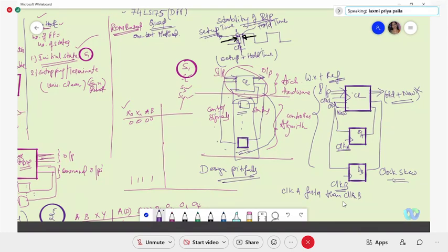That's equivalent to the D flip-flop. Just now someone has given. No? Making the one which is faster, we can delay it using a D element. But decreasing hold time of clock B? Decreasing, no. These clocks we cannot manipulate. Those are the signals that will be coming from the other sources. Actually, clock generating signals are also different circuits. That circuit we cannot manipulate.